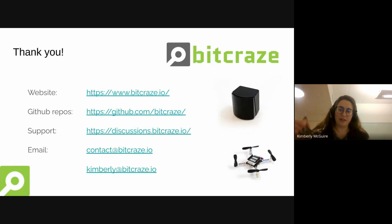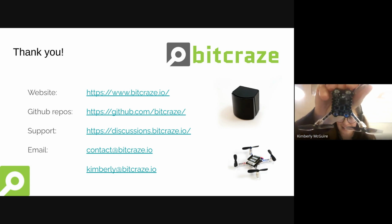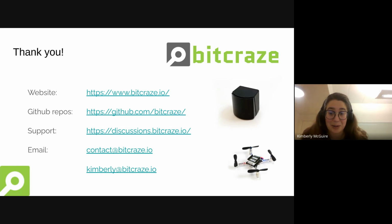Basically, I think these are similar sensors to what the SteamVR marker is using, but you don't see them directly because there's a nice casing over it. These are very similar light sensors. Except we don't have them all over the node. We just have them on a plane, so there are limitations to what you can measure, and you have to assume a flat plane. If you have the base stations here and you're holding the Crazyflie like this, then it's not able to detect the sweep angle very correctly. That's why you would need another base station. But that's where those sensors come from.